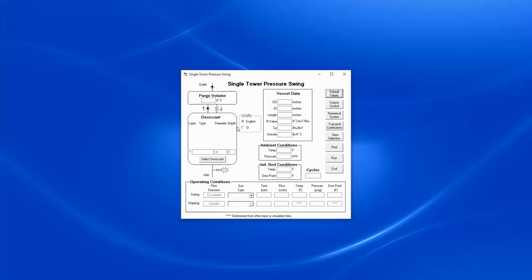When the compressor that this dryer is tied to unloads and stops pumping air, at that point your purge valve would open. The desiccant would be regenerated by this purge volume of air that would flow countercurrent first through this purge orifice and then through the desiccant bed and then through the muffler and out into the atmosphere. As far as the physics are concerned, there's no difference in the 3 types of these dryers. It's just a matter of the actual pressure condition that the regeneration is accomplished under.